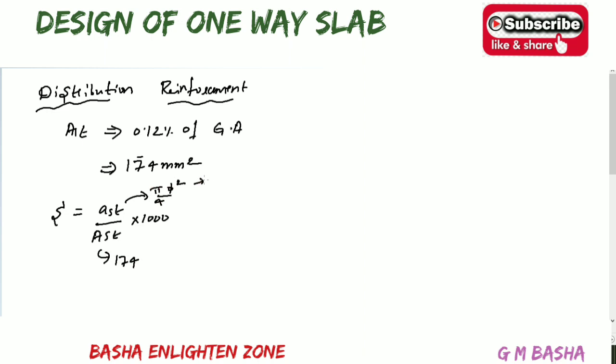For the main reinforcement minimum we are considering 10 mm. But for the distribution reinforcement we are considering 8 mm. Why? Because the minimum reinforcement provided in slabs will be 8. Therefore I am taking the starting value, that is 8 mm. So simplify this one. Pi 8 square by 4 by 174 into 1000, you will get the spacing of 288.8